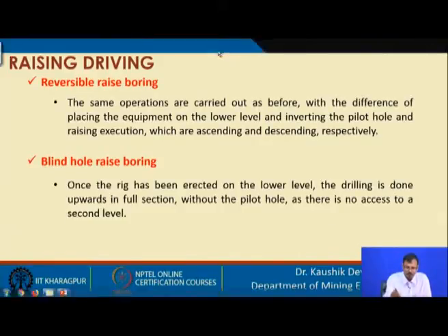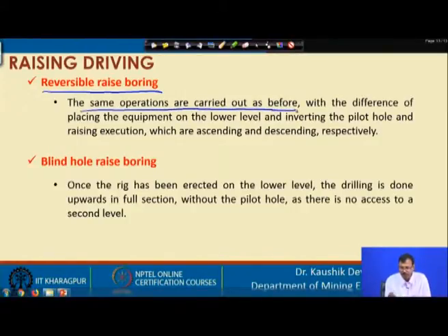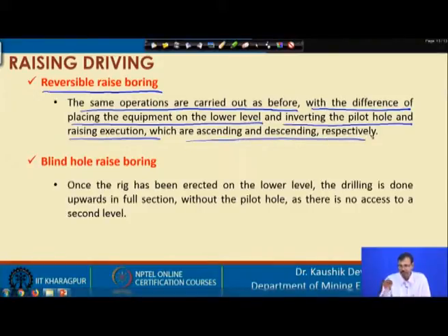In the reversible raise boring system, the same operations are carried out as before, only the difference is that the equipment is placed in the lower level, inverting the pilot hole and raising execution, which are ascending and descending respectively. So, basically if we are reversing this one and place the raise boring machine in the lower level, then the method is called reversible raise boring.